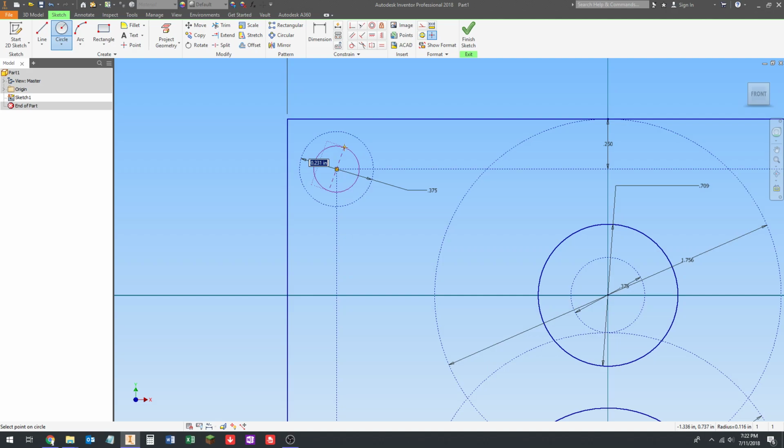So we're just going to create circles and not use a hole feature. I've mentioned it in the class, I'll mention it here. That's not a good practice. The best practice is, if you're talking about holes, you should use the hole feature. And there's a bunch of reasons for that I won't go into here just for time.